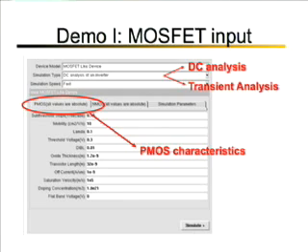to the tool. And as far as PMOS characteristics here are concerned, I have this bunch of characteristics for a MOSFET-like device, things like subthreshold slope, mobility, lambda, threshold voltage, DIBL, and so on and so forth. And this would essentially characterize the circuit.